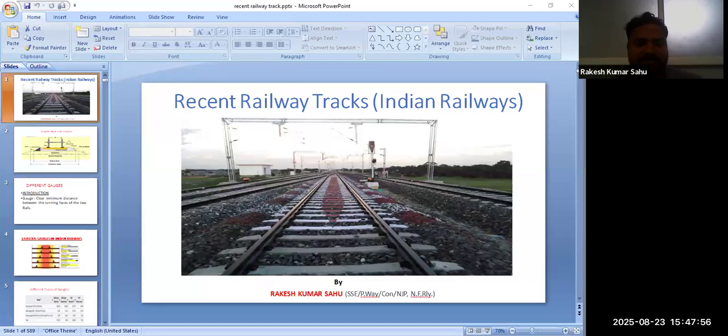These are the 610 normal fish plate and jogger fish plate. It is the 1 meter long fish plate which is used in LWR, long welded rail laying, and in SWR, short welded rail laying. Basically, this 1 meter long fish plate is used nowadays. The rest of the plates are obsolete nowadays.